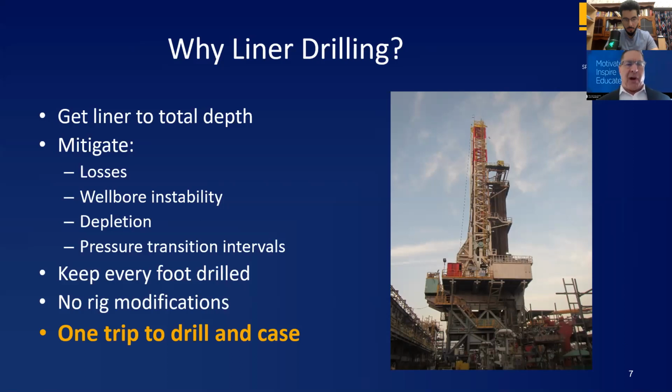Because of the close proximity of this pipe to the hole, you get what we call a smearing or plastering effect, mainly in sand-shale sequences, because cuttings circulating up from the bit are getting plastered into the formation, which gives you almost a perfect particle size distribution against that permeable formation. That's the reason we think we see a lot fewer losses in casing and liner drilling than we do in conventional drilling.